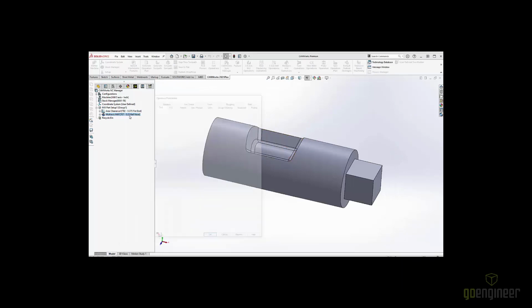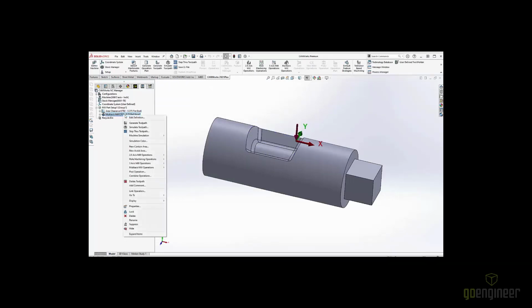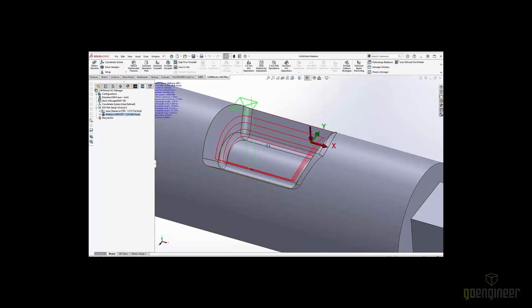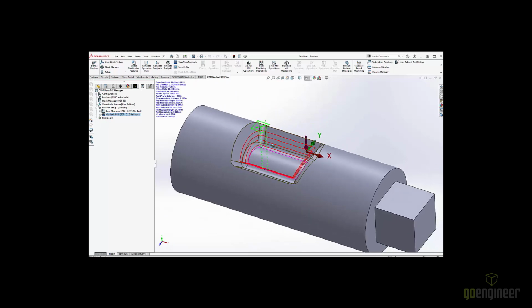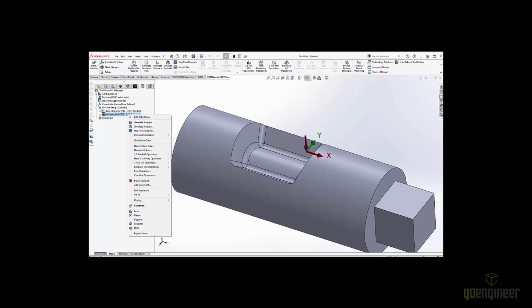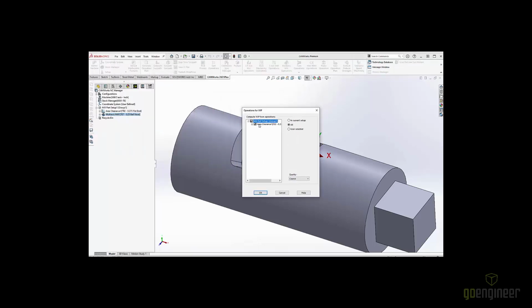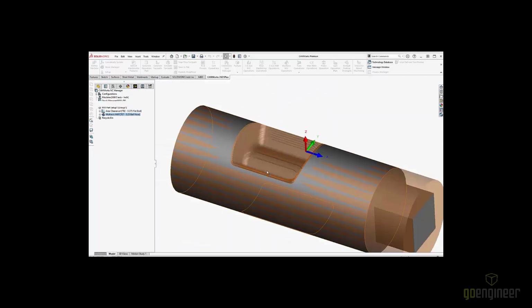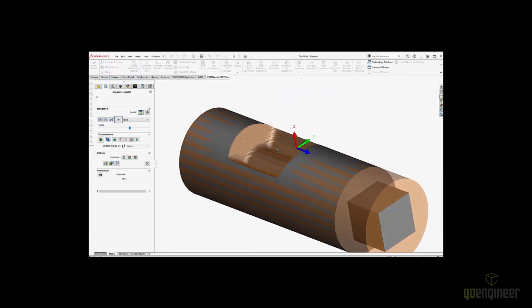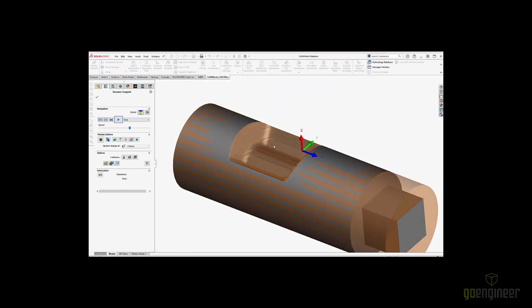But just running the simulation of this guy real quick. If I were to simulate this, I'm not going to have the area clearance done first. I don't want to make you guys watch the area clearance. So I'm going to use a little trick here: before I click simulate, I hold down my shift key. And what that does is start the simulation from a work in progress, WIP. I'm going to say start this simulation as if the area clearance is already cut. All right, so we start in a much better place to really observe what this toolpath is going to do.